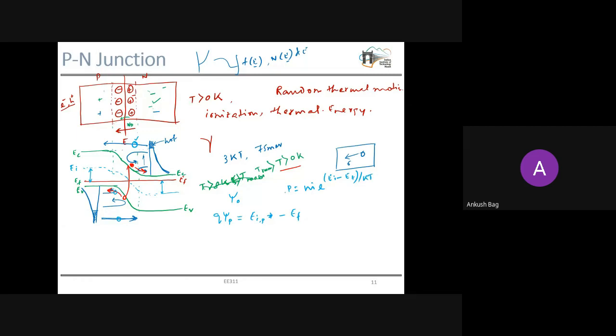Okay. So now whenever we increase the temperature, first all the dopant atoms will get ionized, because again we know that the EA energy level and ED energy level are very close to your conduction band and valence band. So the electron and the hole will move easily from that energy level. So the number of holes is almost equivalent to the acceptor dopant atoms, Na.